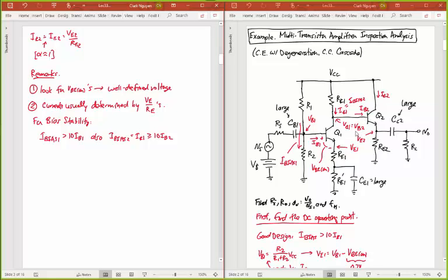And in your lab number 6, you actually may have 4 transistors in series here, in a cascade like this. And so each time you go from one transistor to the next, make sure that the collector current for the previous transistor is 10 times higher than the base current for the next. And if you do that, then you're going to have a nice stable bias point. If you don't, you may run into some issues. You may not. But at least for the design, we're looking for a good design for lab number 6. We want to see that in your lab number 6 design. And of course, you're already getting experience doing that in your lab number 5.